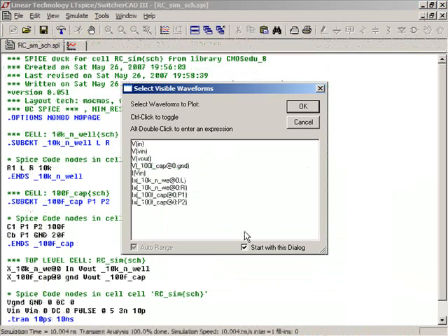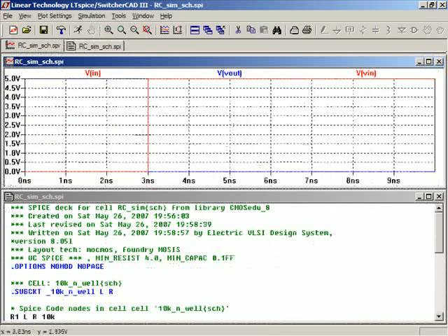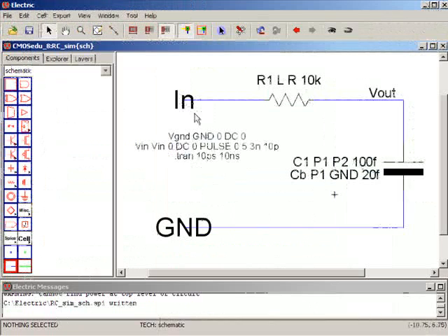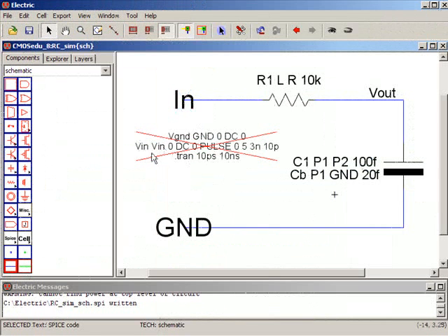And there it is. And plot Vn. Whoops. V in, Vn out. Well, I don't know what Vn is, so I must have an error. So we'll hit OK. And so I've got something mislabeled. So let's redo. Let's go take a look at my nodes. Oh. So I called this node in, or this export in, not Vn.